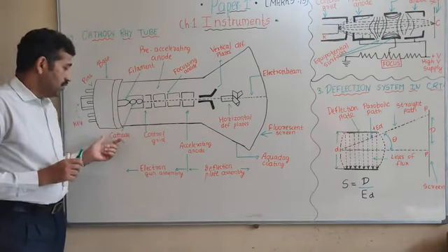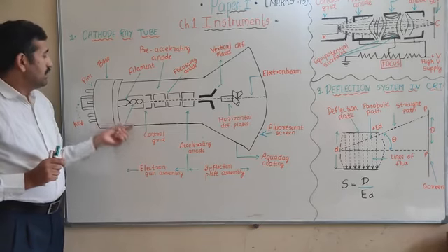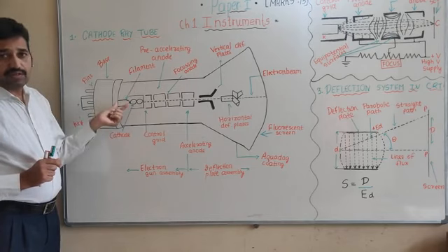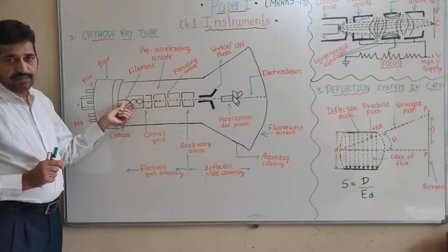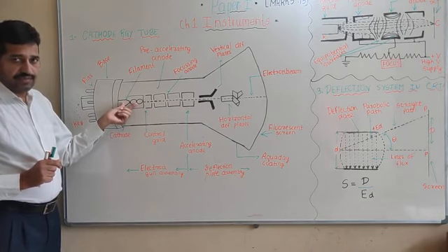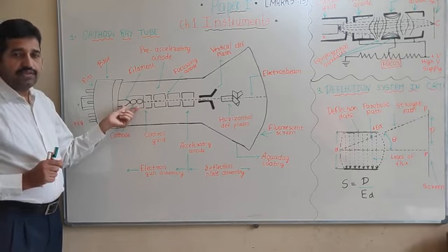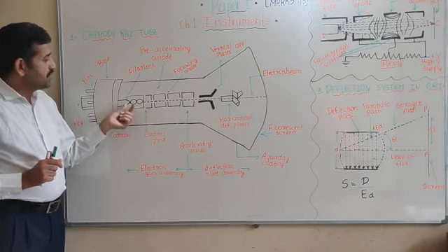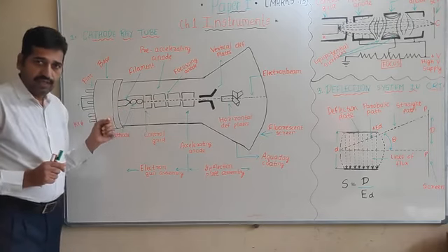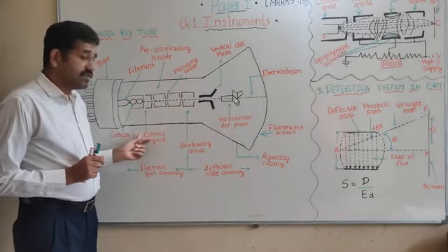Now, how does the electron gun assembly play its role? When the filament becomes hot, the cathode is mounted onto the filament. The cathode is given a very high negative voltage. Since like charges repel each other, electrons emit from the cathode and spread towards the front. But these electrons should be converged at the center. It requires the control grid.